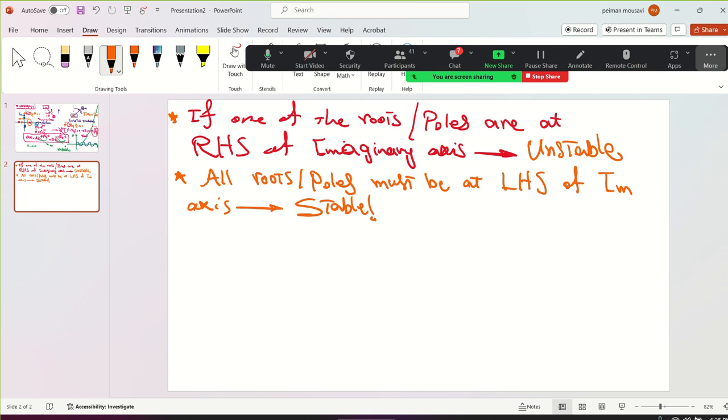This is a very practical way of helping a person understand how to go from a nonlinear differential equation, linearizing around the equilibrium point. What is the equilibrium point? Using Taylor series expansion, you get a linear differential equation, then solve that and judge the roots or poles in the complex plane to tell about stability, instability, or a marginally stable system.